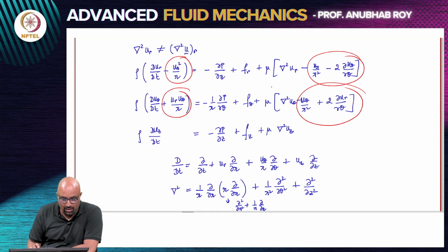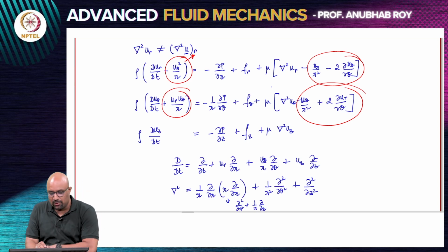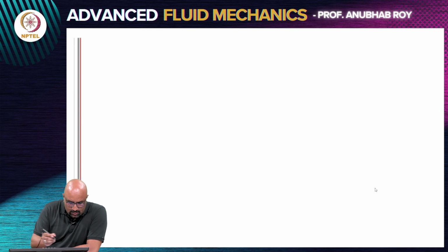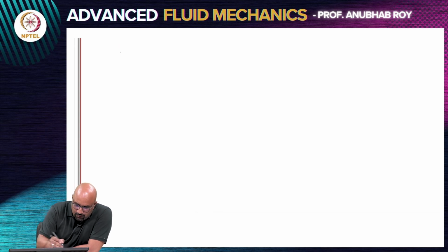So, you apply a curvilinear coordinate system, and this term, if you are familiar with it, should remind you of the centripetal acceleration. When you are writing down your flow in curvilinear coordinate system, there is going to be an acceleration by virtue of the fact that you are moving on a curvilinear track, and that is basically your centripetal acceleration that is there in the problem. So, with all of this, right now we will attempt the pipe flow problem. First, what we will do in the pipe flow problem is list out our assumptions. So, flow through a circular pipe.